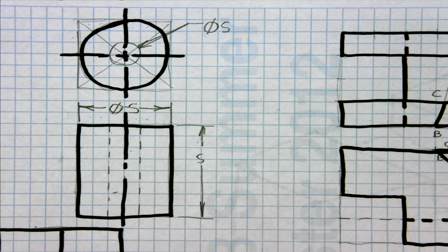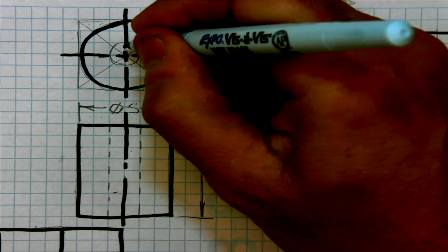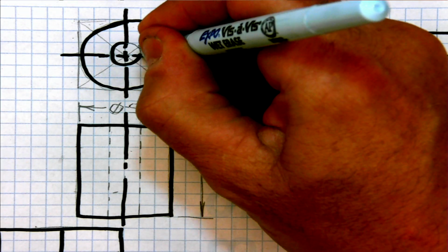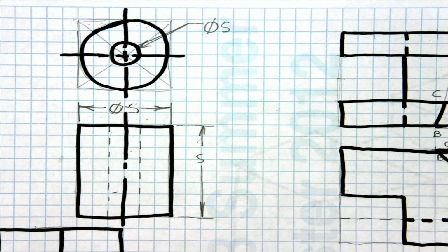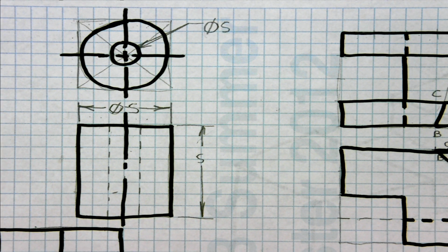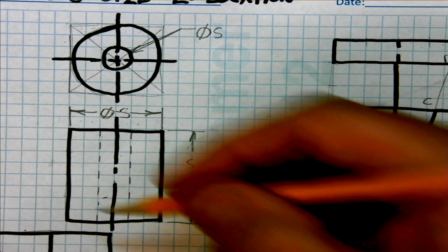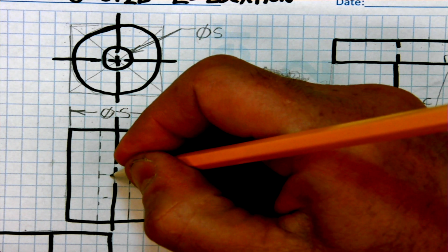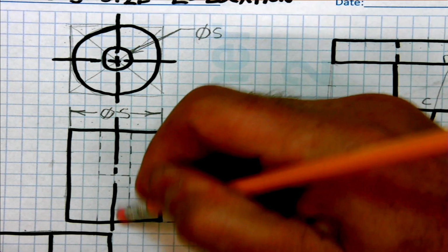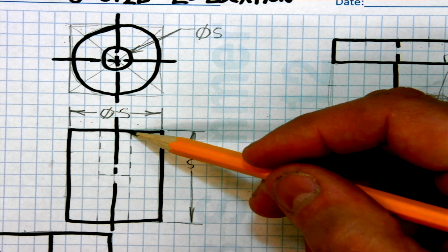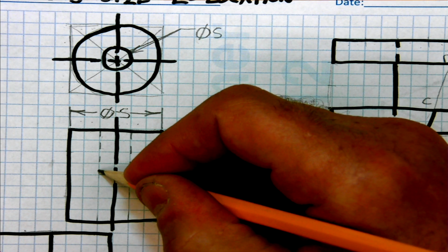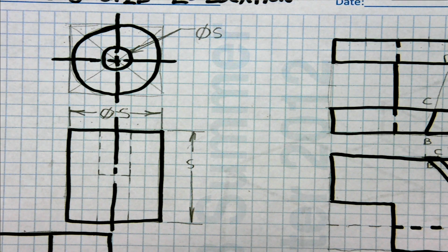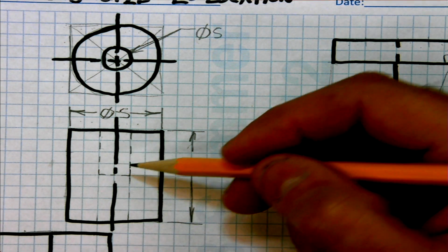But now let's say that this hole does not go all the way through the object. It's called a blind hole. So let's say it just goes 4 blocks down and stops. Okay? So now this dashed line is no longer here because now we're just saying that the hole goes down 1, 2, 3, 4, and again this would be an L shape right in here, and it actually stops. Well, then you have to tell the person what the distance is going from top towards bottom.